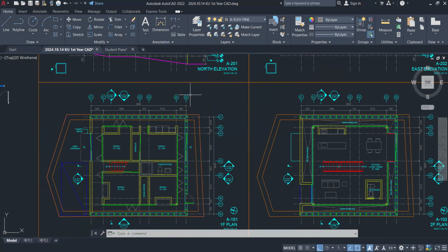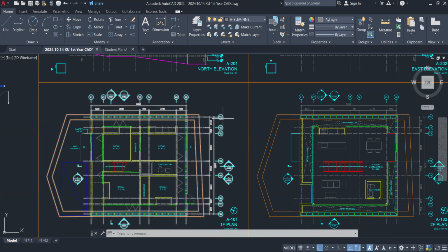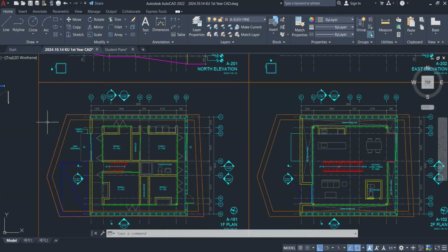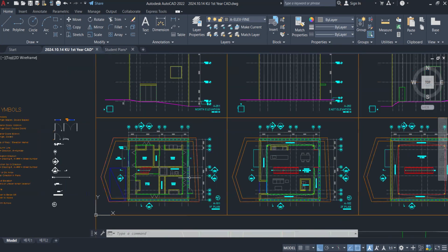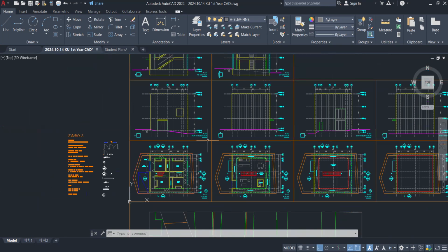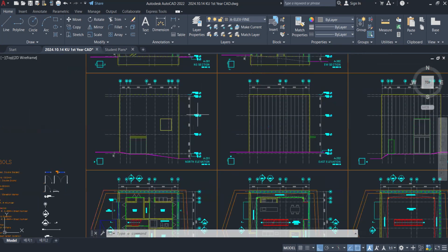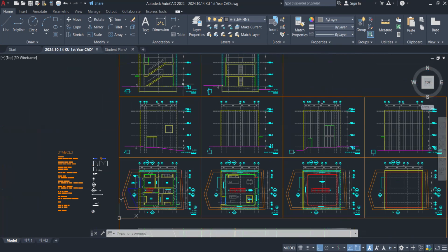Typically, the X column markers are always on the top, and then the Y's are always either on the right or on the left. It just depends on where you find it convenient to place them. But that should be true for all of the indicators. As you can see, as I've placed all the markers on the right here, all the top of slab markers are also on the right. So you need to be consistent in your layouts. You notice the consistency of these.